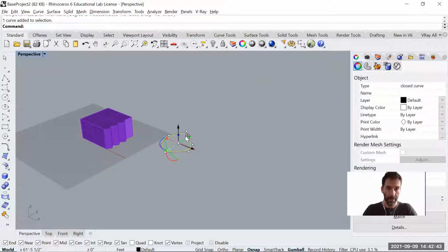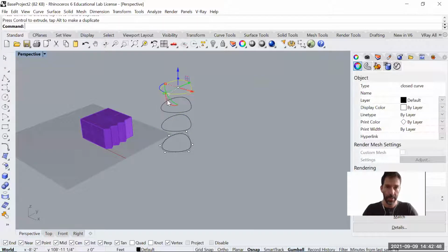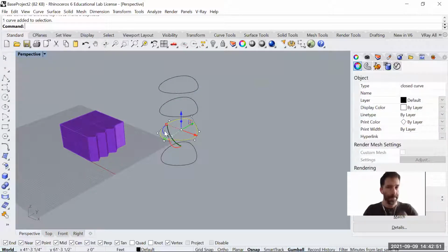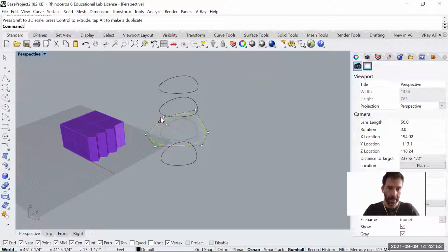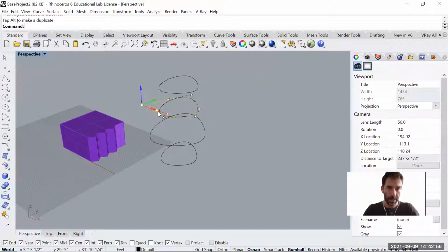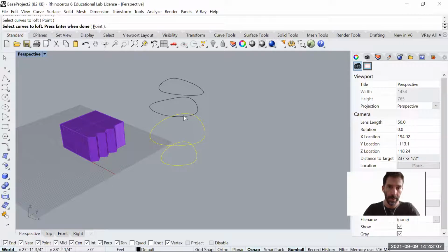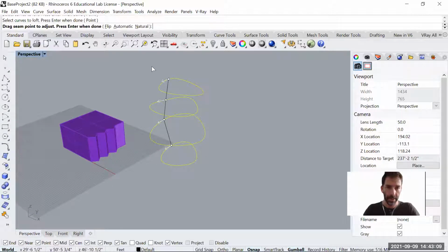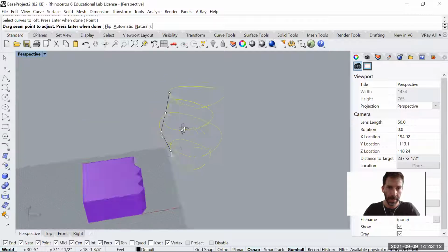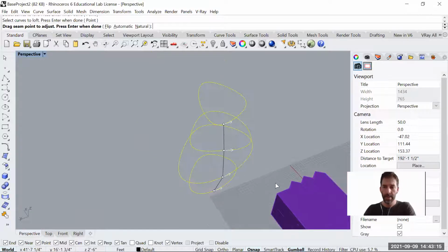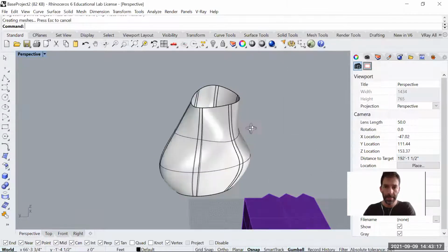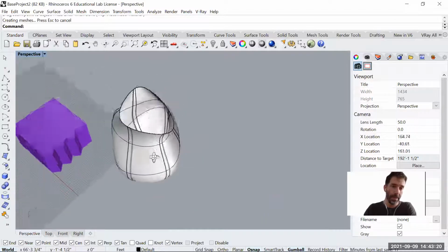For example, this curve, I'm going to copy, pressing Alt, blue arrow, copy, again dragging up while you press the vertical axis, and then I'm going to scale them or move some points to make some slight variations. And loft. Select one by one in order of the loft and in the same area. It gives you this curve. They should come along in the same area and with the same direction. And then you say enter. Okay. That gives you like a little base or something.